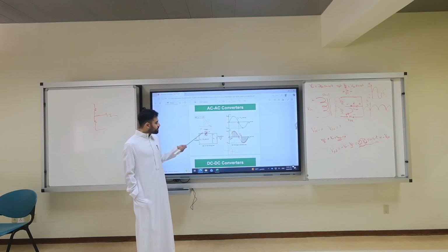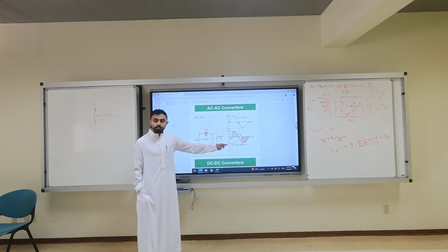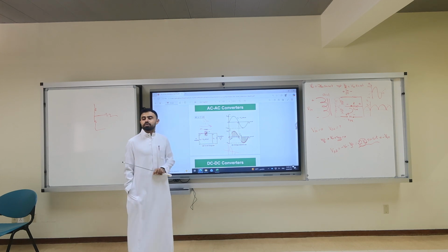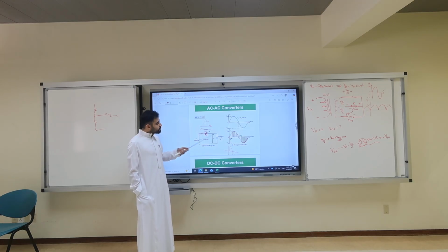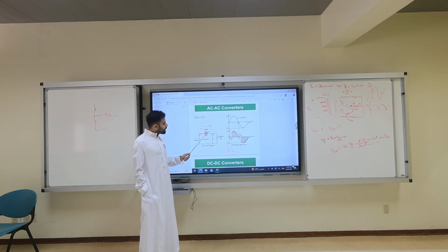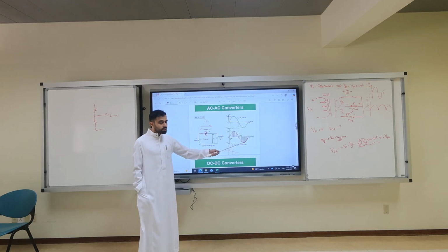Remember, this is your V. This is a different circuit. This is just diode, battery, source, resistor. The V output equals V input if this is on. Always, the output equals the input as long as the triac is on. When the triac is on, apply a positive gate when you have positive input, and apply a negative gate current when the input is negative.